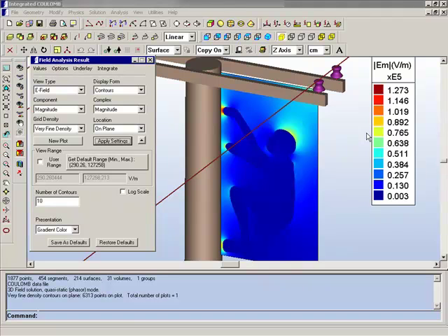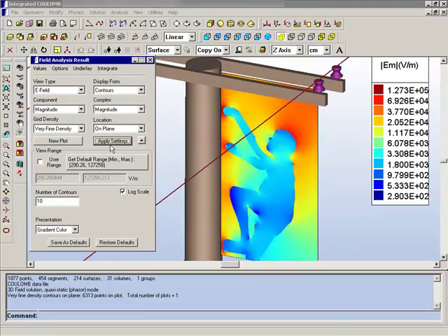However, a lot of people may be concerned about the fields inside the body, even though they're much smaller than that. The fact that they're inside the body, lower fields may be considered a concern. By switching to the log scale, the plot now shows much broader red areas because the red covers a larger order of magnitude, but now you can clearly look inside the body and identify colors such as this shade of blue with a particular value of the field as well.